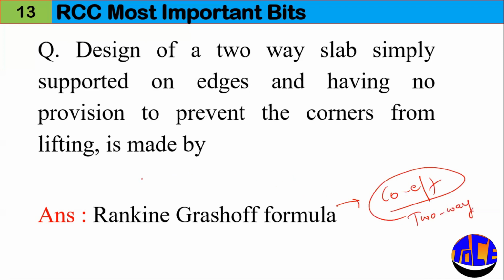For two-way slabs that the corners prevent from lifting. So no provision to prevent the corners from lifting, moment coefficients are provided by this Rankine-Grashof formula, so that we are going to use for the design of two-way slab.